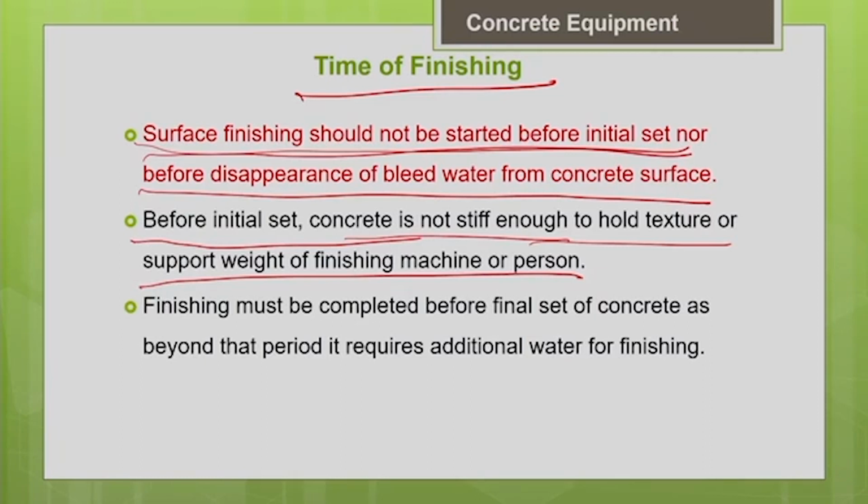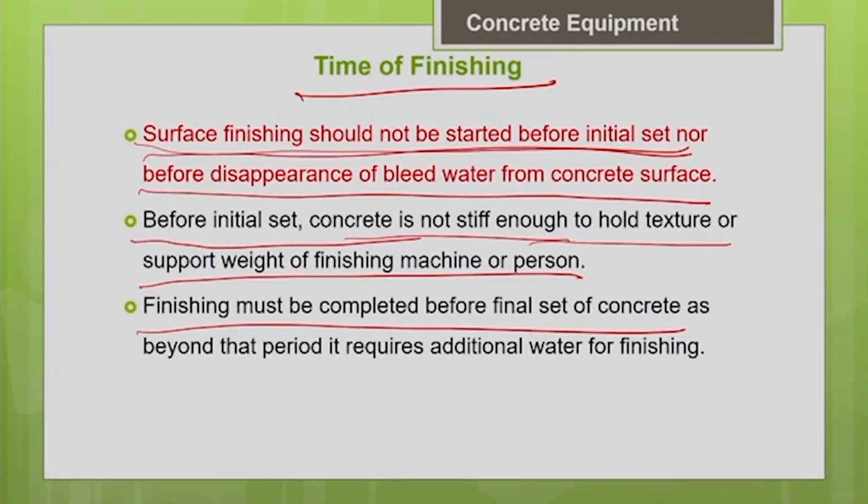After the initial set only, you should start the finishing operation, and finishing must be completed before the final set of the concrete. After the final set, if you try to do the finishing operation, you may have to add additional water. But adding the additional water and manipulating the surface of the concrete will definitely affect the surface strength and the wear resistance of the concrete. So we should complete the finishing process before the final setting, as beyond that period it requires additional water for finishing, which is not advisable.